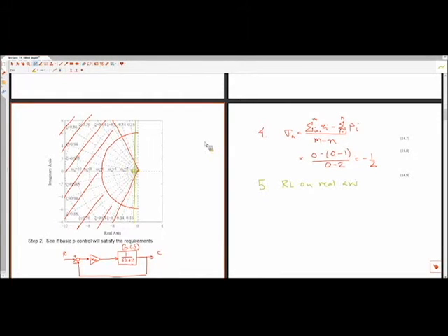closed loop poles in this region? And the assessment you should be making here, we can talk about more complicated ones if we get to examples like that, but the simple assessment here is that this green line, the root locus, never intersects the region of the closed loop plane where we want the poles to be in. So with a simple proportional controller, we cannot achieve the metrics. So this is a pretty easy way via this graphical method called the root locus to understand, all right, will proportional control ever get me there, or do I need to do something more complicated? So in this case, the answer is no.